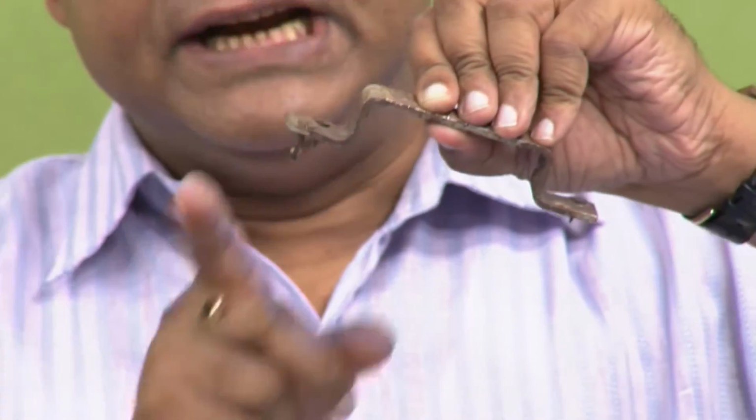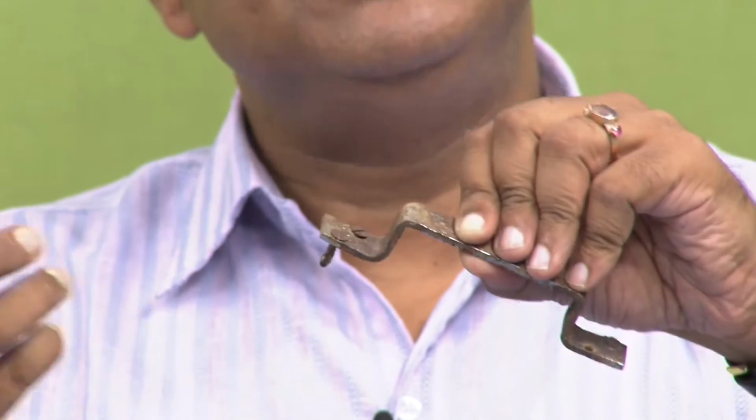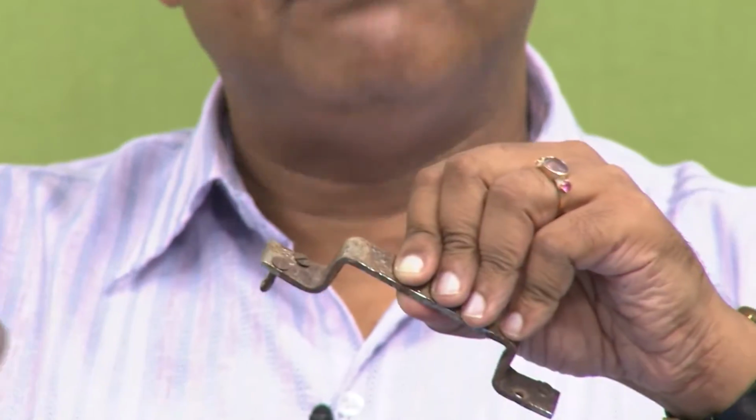The bottom part has entered into the wood, and we assume the wood is pervious, because there are fibers that can hold moisture, or the moisture can enter into the wood over time. So we have an electrolyte, and they are electrically connected, because here also we have moisture.